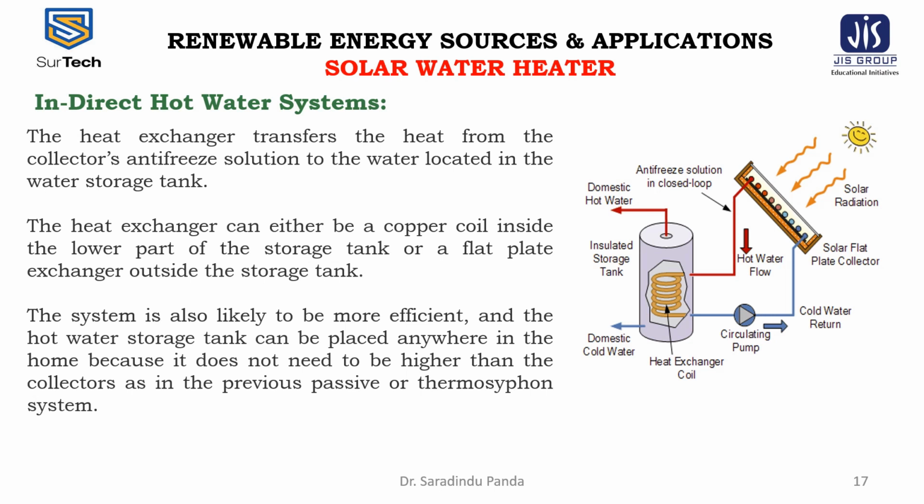as most homes use gas or wood fired boilers as well as a hot water storage tank with a built-in heat exchanger. One disadvantage, however, is that the closed loop system is dependent on electricity for the circulating pump, which may be expensive or unreliable.